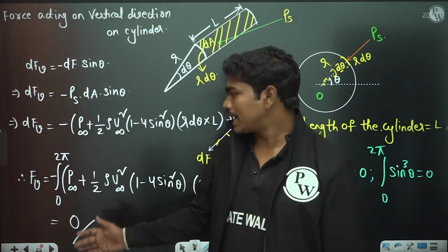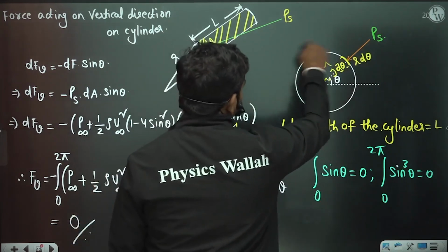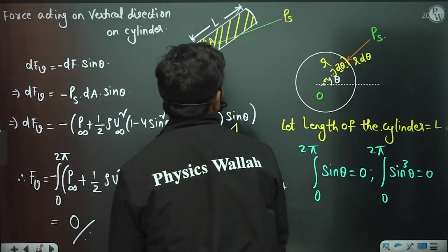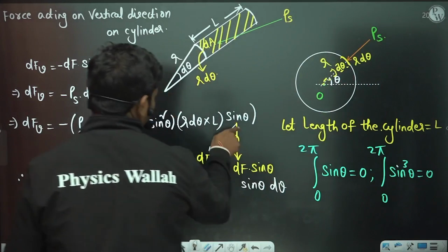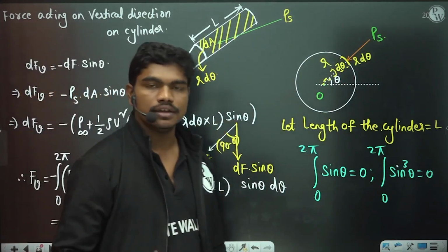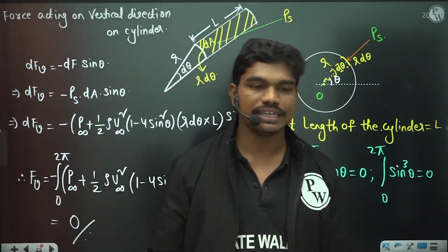And if you try to calculate the drag force, then definitely you can calculate it. For example, if you resolve this in this particular direction, let us suppose the fluid is stationary and the cylinder is moving with some velocity, then this horizontal component is minus dF cos theta, and if you integrate, you will get the expression that we have given you, half CD A u infinity square.